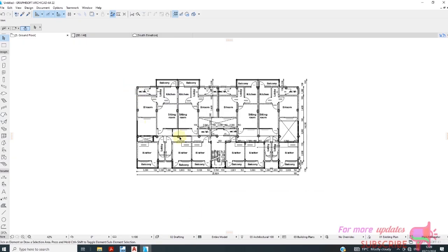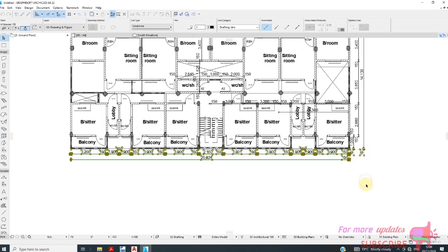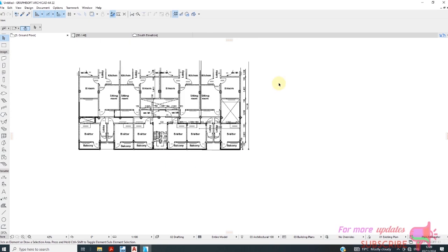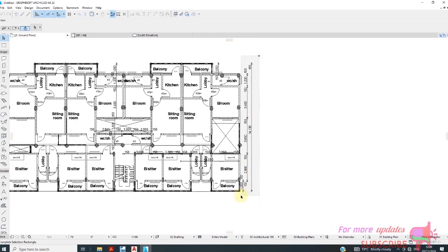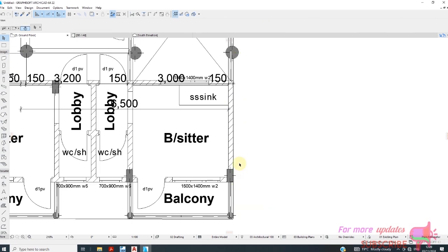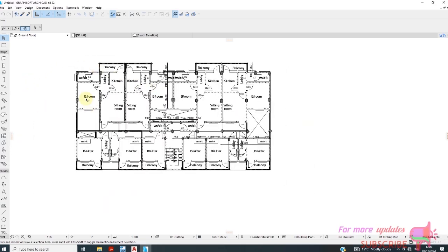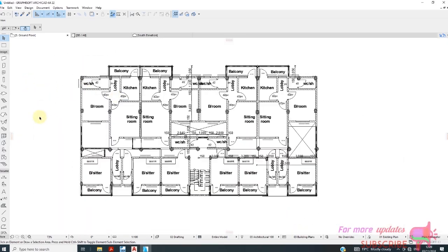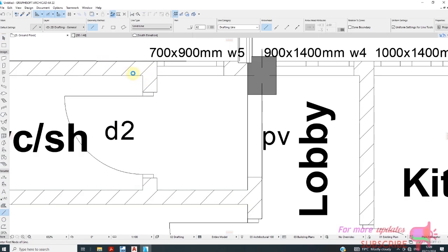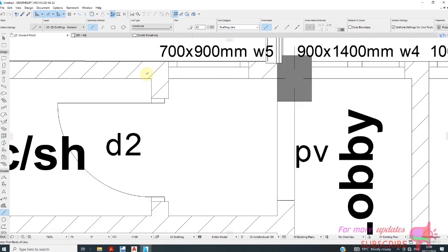So there's a lot of work to do here because I need to create a lot of grids. They're going to help me to model my beams and my columns without errors. Because if you don't model properly in Tekla Structure, you will get what we call validation error, and design cannot be done. So I will go and start creating my grids. I'll activate line tool. The first thing is you need to know that grid lines are always at the center of walls. So these are walls. So I need to draw grid lines at the center of my walls.